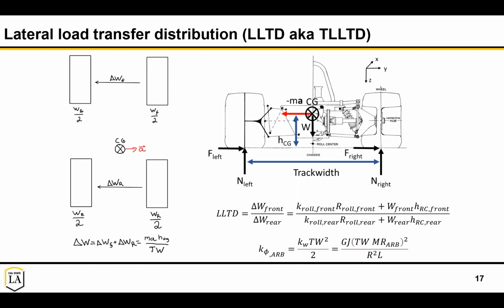So that's a little bit about getting your lateral load transfer distribution and getting the balance of your vehicle right. And so in the end, you'll want to make sure and go back to that you're not having too much travel, that you're not bottoming out your suspensions.